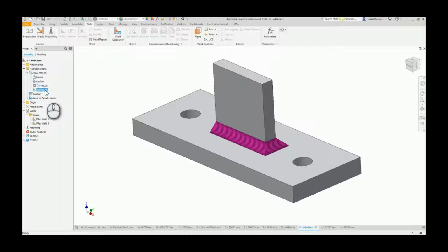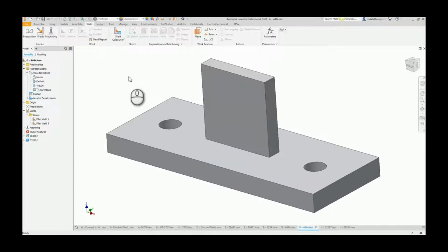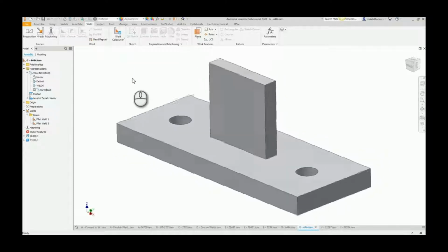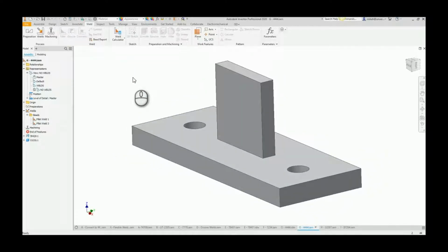Then the last view representation we create, or view rep as we call it, is one with no welds. And pretty much the reason for this is to save some video crunching power. We're not creating the extra surfaces of the welds, and as well as when we're shaded, not showing the weld bead texture. So it's basically to lighten up the model, especially when you get it in large assemblies. And we also utilize it on IDW when we're actually putting the dimensions to show locations of parts.